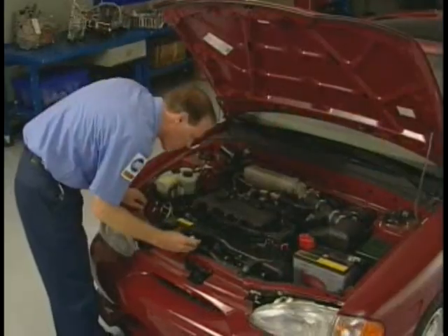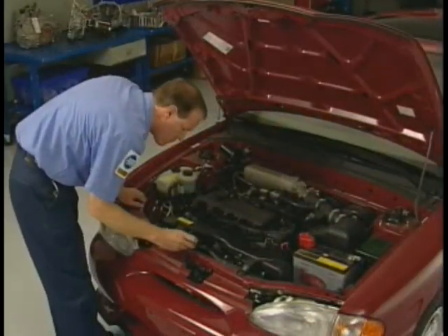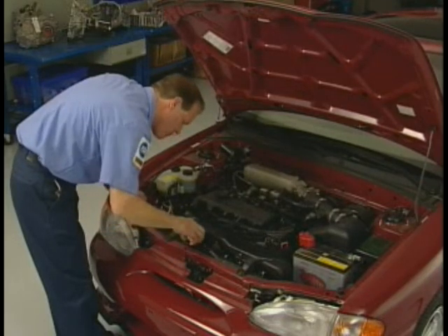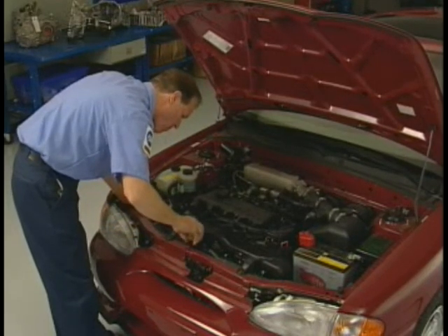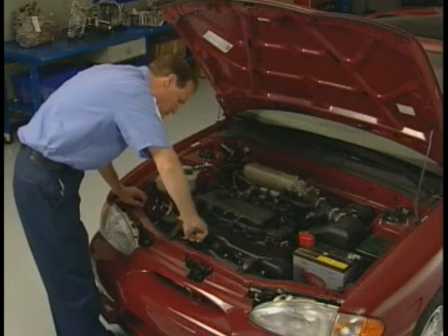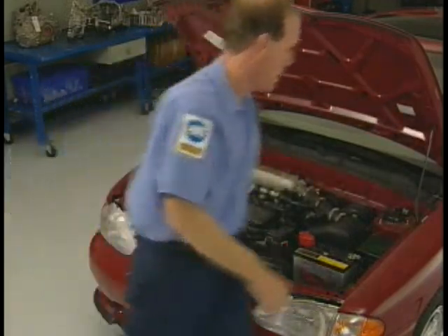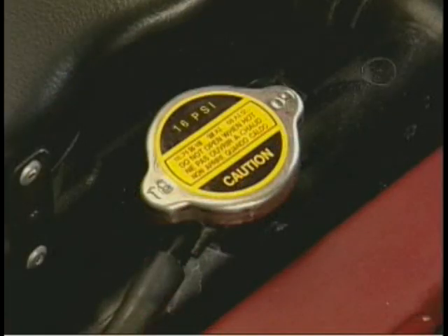For automotive applications, the converse also holds true. If a system is put under pressure, the heat saturation point is raised, and the liquid will be at a much higher temperature before turning to steam. Automotive cooling systems use pressure to transfer heat more effectively. Each pound of pressure applied to a cooling system raises the boiling point about 2½ degrees. A system under 16 pounds of pressure will not boil until about 250 degrees Fahrenheit.